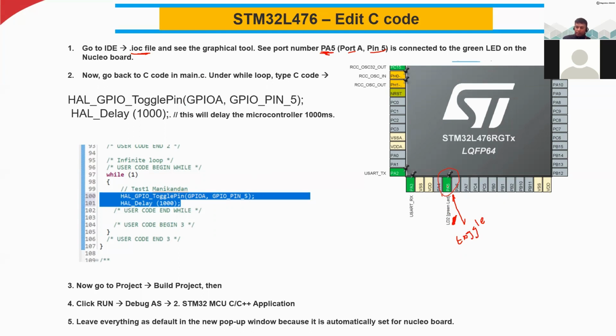So I assigned green LED. I just left click and then you will see the box and then you have to assign this for the LED. And you should know the name. How can we name this? For example, this one PC4, right? It means it is indicating port C and pin number 4. Port C, pin number 4. So for each pin, it has the same meaning.